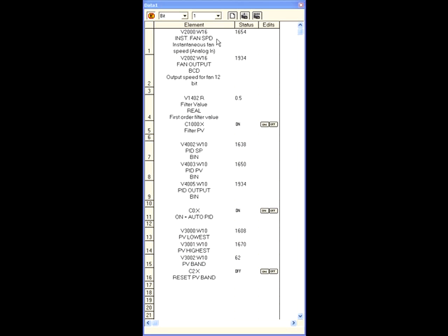We're actually getting this from a fan which provides a 0 to 10 volt output based on the speed, and it's being controlled by two other fans that we're driving with the next value, which is V2002. And this output drives the two fans, they blow the other fan, it spins, and we get a closed loop PID that way. Both values are quite noisy because that's the raw value with no filtering involved coming straight from and to the analog card.